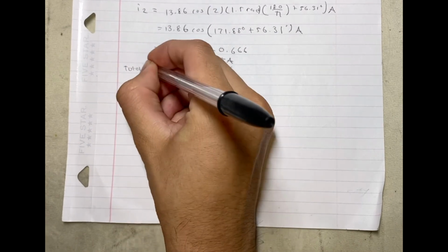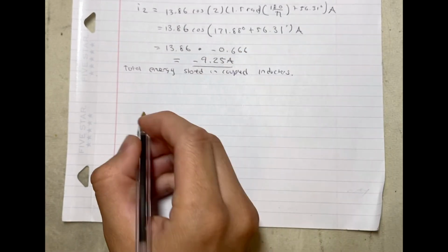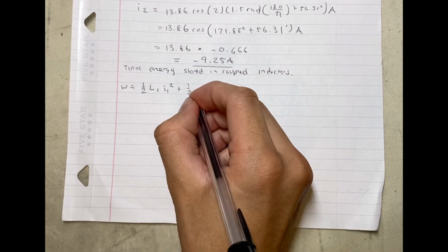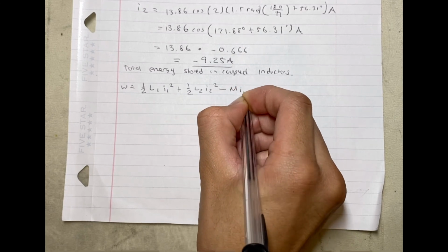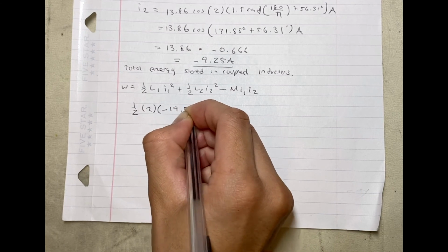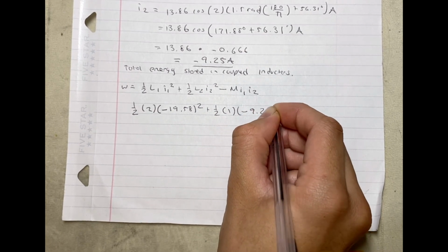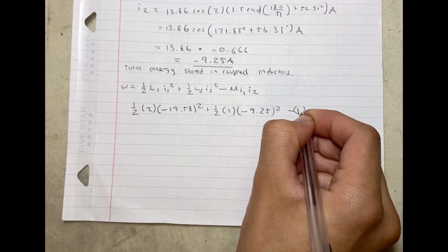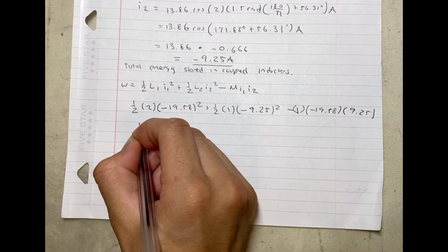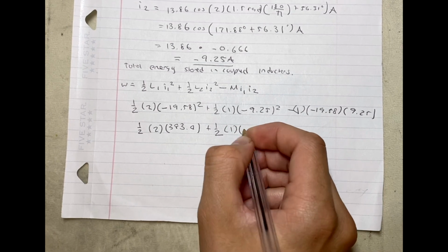Next, we need to find the total energy stored in the coupled inductors. For this problem, we'll be using the equation W is equal to 1/2 L1 I1 squared plus 1/2 L2 I2 squared minus the mutual inductance times I1 times I2. This becomes 1/2 times 2 times negative 19.58 squared plus 1/2 times 1 times negative 9.25 squared minus 1 times negative 19.58 times 9.25. This simplifies to 1/2 times 2 times 383.4 plus 1/2 times 1 times 85.19